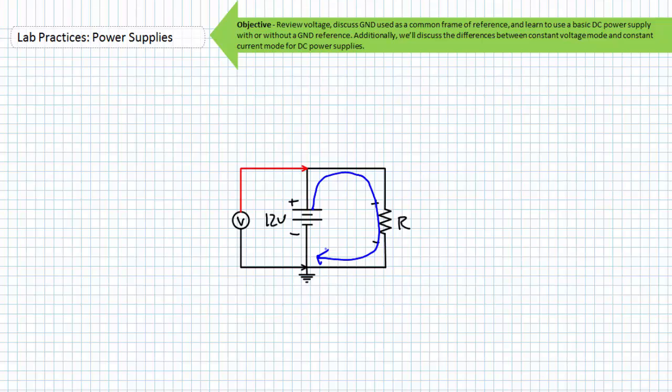it gets weird. Because the negative terminal is hooked to ground, current will travel anywhere ground exists, meaning the whole ground plane could theoretically be your return path. This sometimes vastly simplifies complex schematics. I know it does not look like there's a complete circuit, but realize those two symbols imply a single point of common connection. That point of common connection being the whole ground plane.